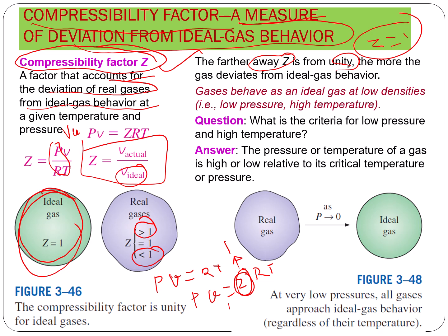In most of the cases, for the gas to be considered as ideal gas, it needs to have low pressure and high temperature. So if you have a low pressure and high temperature, most of the time you can treat it as an ideal gas, and you can use the ideal gas equation. You don't need to take into account the compressibility factor. But if it is a high pressure, in that case you cannot use the ideal gas equation.